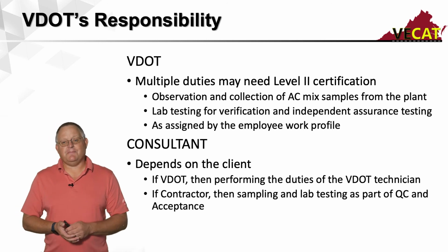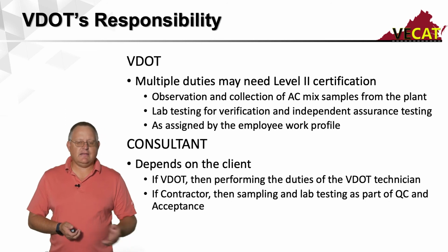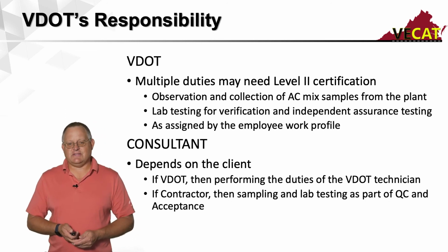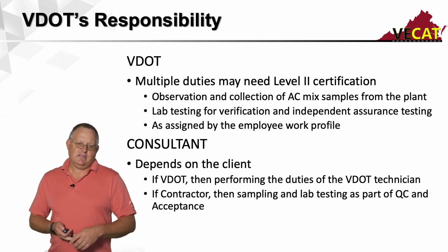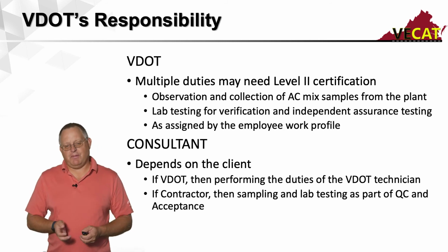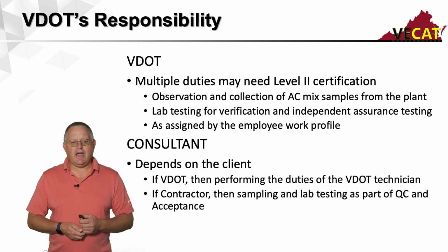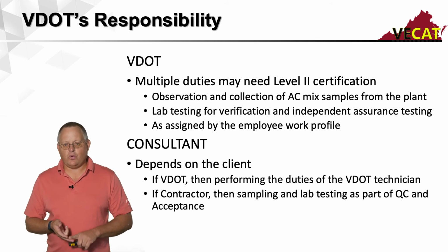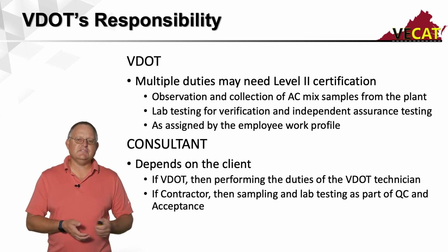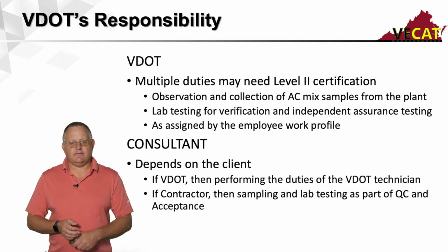If you're a consultant, it really depends on who your client is. If you're a consultant and you're working for VDOT, you may be performing the same duties as that VDOT level 2 technician: observing, collecting samples, watching tests being run. It's very possible you might be able to take that sample back to your credentialed lab. If you're the contractor and that's who you're hired for, you're doing what the contractor's person is doing. You're sampling, you're quartering, you're testing, whatever's needed for the quality control and acceptance portion of the process.